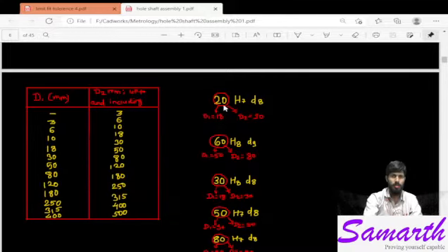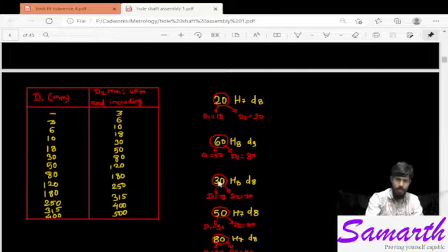Let us say our given designation is 20 capital S 7, small d 8. That means this diameter falls in the range of, here you can see, 18 and 30. So we will take 18 as the lower diameter, which is D1, and 30 as the higher diameter. If 30 itself is given in the designation, let us say,